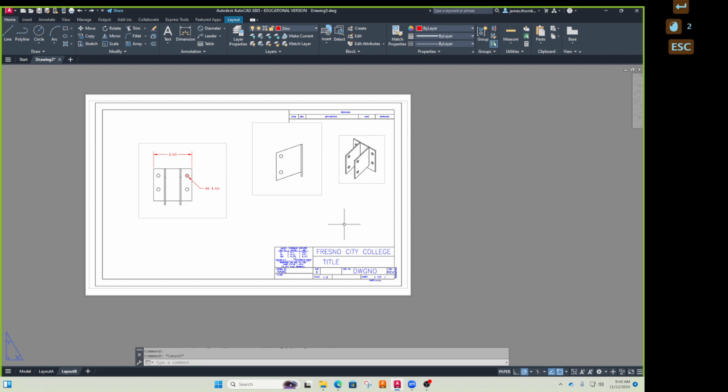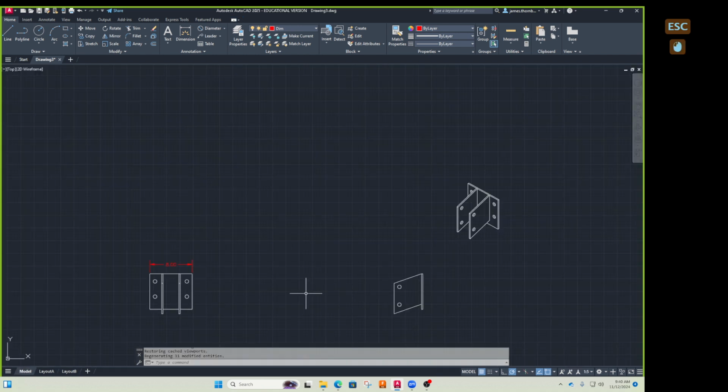Okay, so I just put it there. Just move. I can't pick it. Why can't I pick? Yeah, because I want to move the viewport, right? Pick the viewport. The viewport's the window. I don't want to move my parts, because if I just make a big viewport and I move this stuff down, it's not being lined up here anymore.